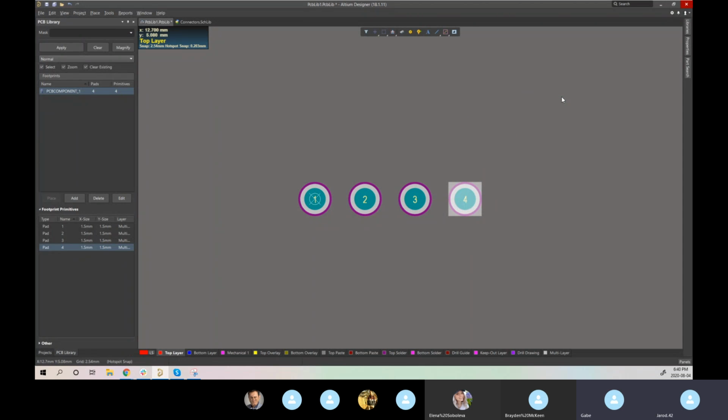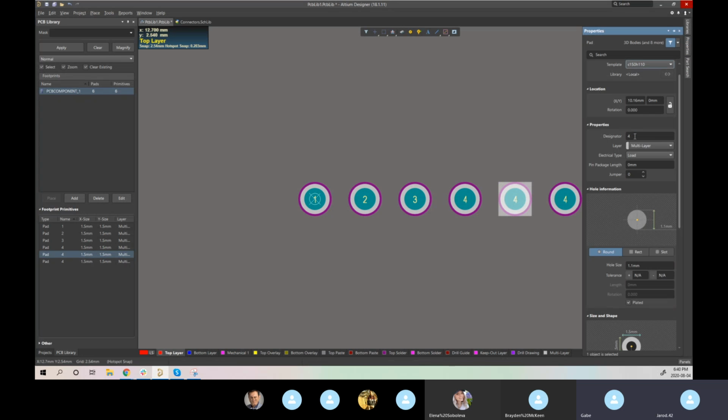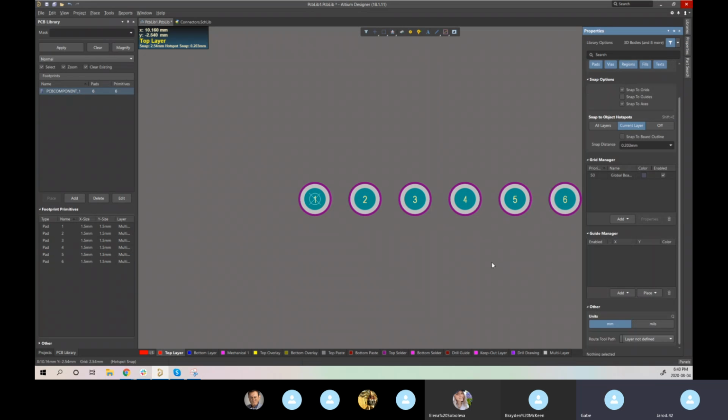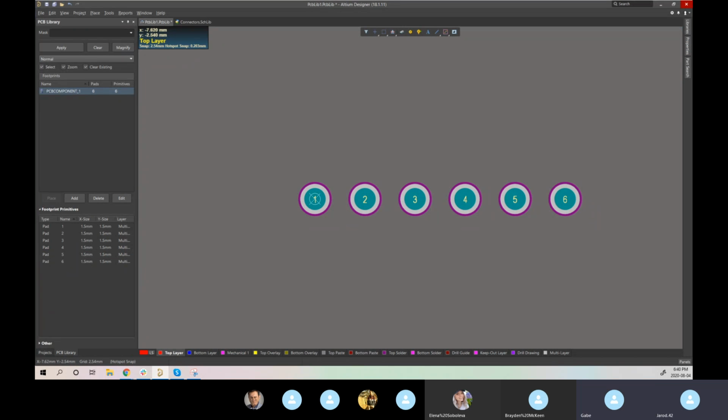So if I were to just click it over here, and then I go to Control Paste, you can see that it's wanting to be way over here again. So if you are going to copy paste something, you want to make sure that you're doing it off the center reference. So when you're placing your next, you're placing it about its center as well. You do just have to make sure when you're doing this, you go change the number, since it'll have whatever it was. Do you want to show them paste special or paste array?